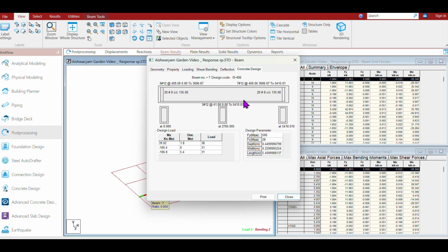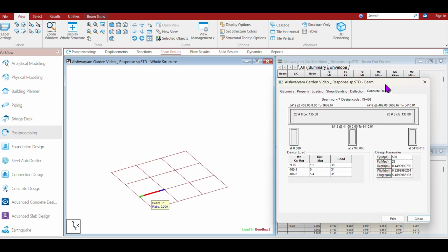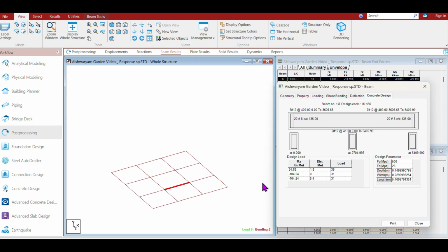The 12 mm itself is not the most required thing. You calculate the area of reinforcement and suggest your own idea using 16 mm rod or whatever you feel is better. So for this beam, it comes, next beam. The 7 numbers of 12 mm rod come up in the upper floor. Bottom it reduces. Next, see here it is also 12 mm, 7 numbers coming on the upper side. In the bottom it comes lesser.